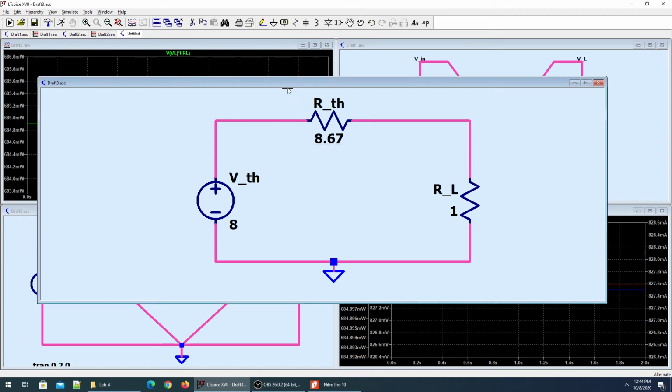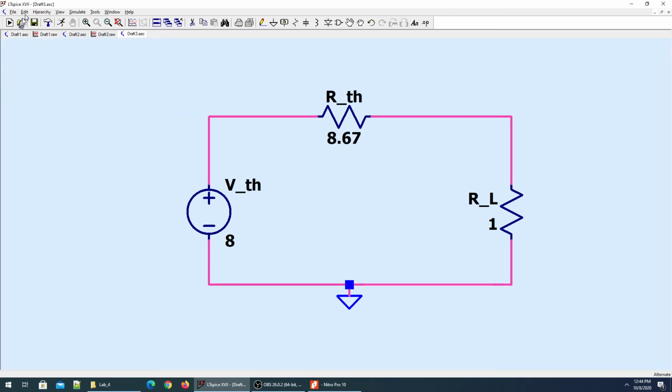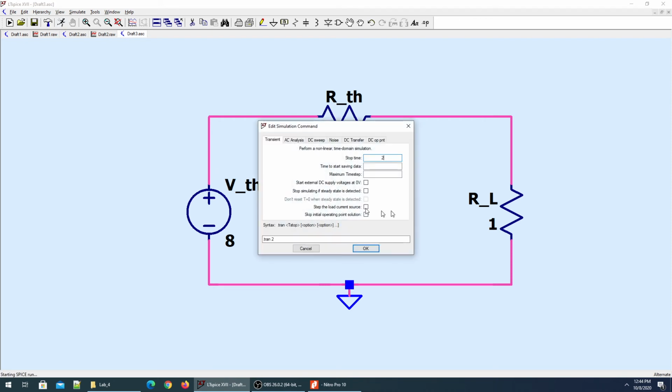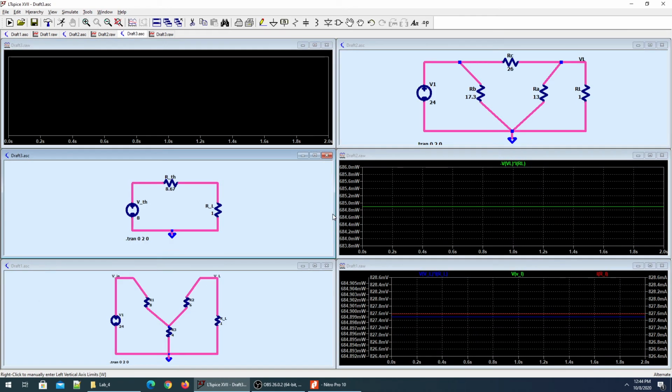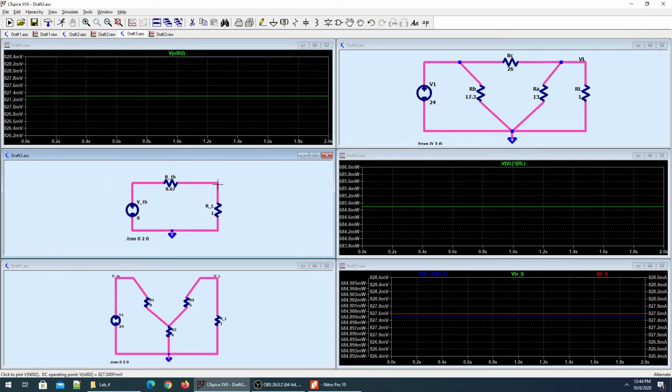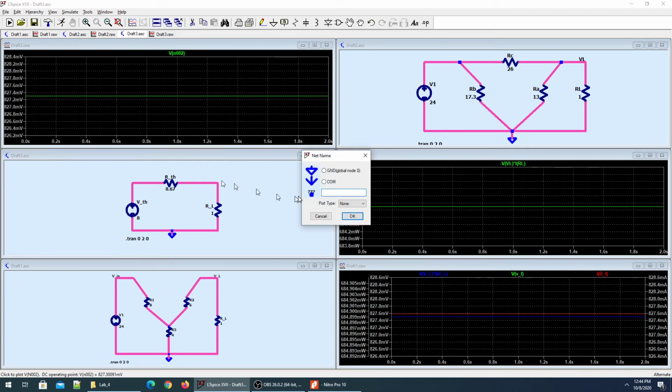You can easily calculate that. There's no problem with that. Let's run the simulation for 2 seconds. Actually, even 1 second is okay. I have made myself a habit of putting the rubber tool. Okay, so this is the circuit here. Let's see the voltage. As you see, the voltage at node 002, which is here, I'll call it B.